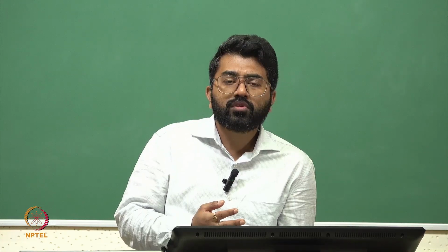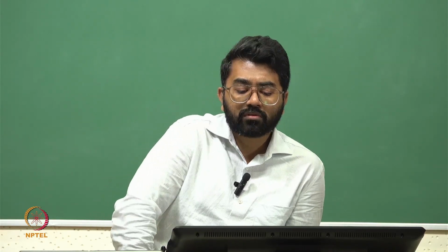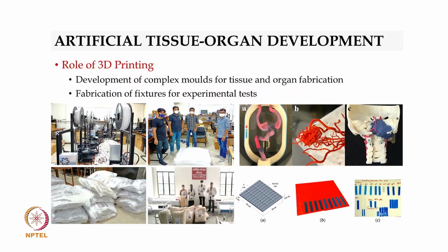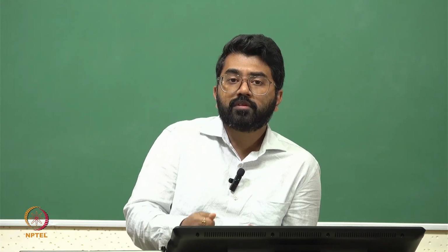But the idea here, which I want to highlight, is we are now focused towards the development of the different soft tissue mimics. As you can see on the right side, you're looking at some arterial networks in the B section, and we're also building some molds for generating these test specimens. This was designed in SolidWorks, and then finally the red part is the mold, and you're pouring a liquid which is silicone in this case, which has a mechanical property tuned specifically to human skin, and then you take out the specimens or the samples and you test them all on a UTM, right?